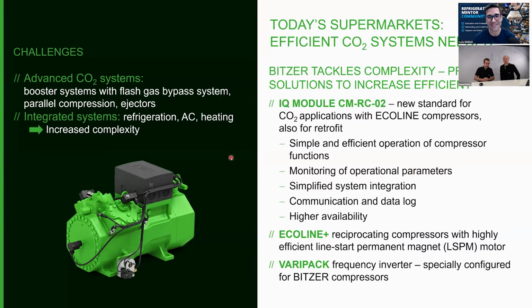When we implemented the Varistep technology, we also added our Bitzer OLM IQ. That's our oil management system, which works in combination with the IQ module. This oil management system can record the oil level in the compressor. It's not only a device that feeds back oil, it's also a digital sight glass you can see. And you can see the sight glass history in the data log over 2 weeks.